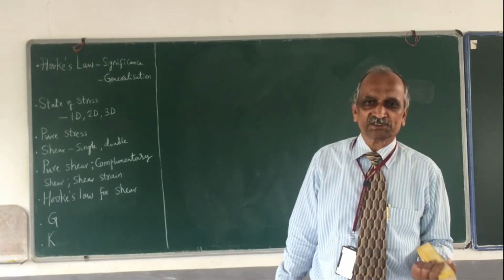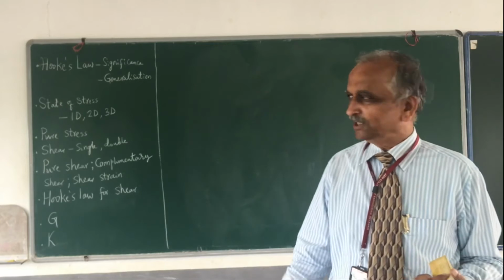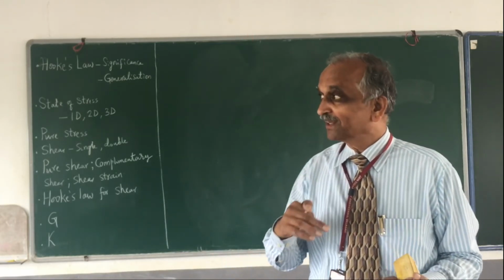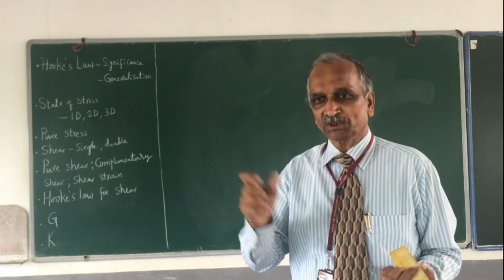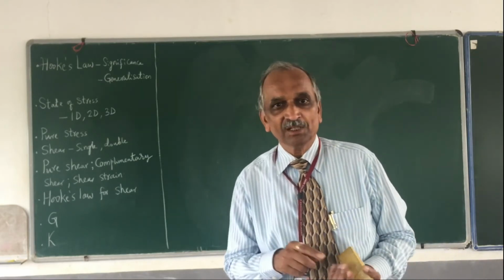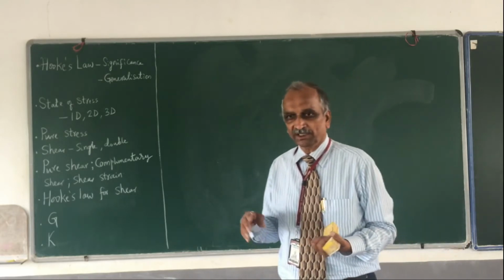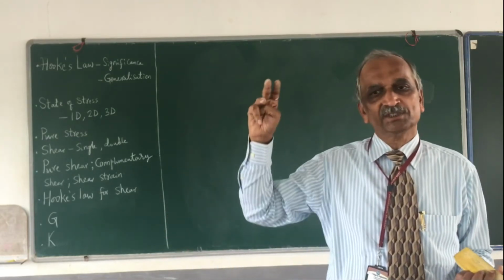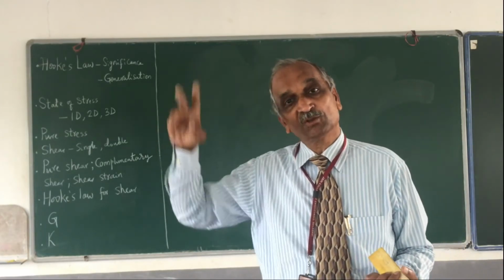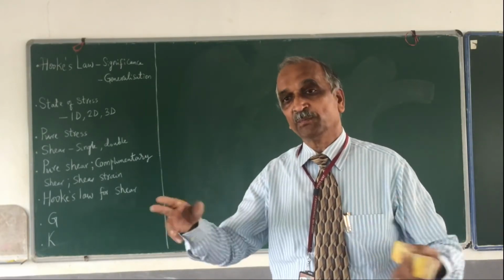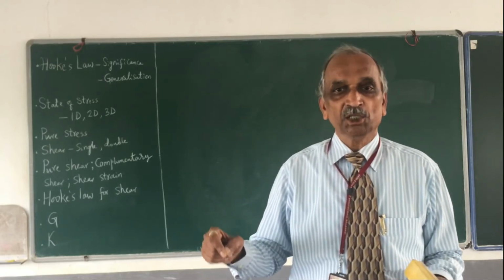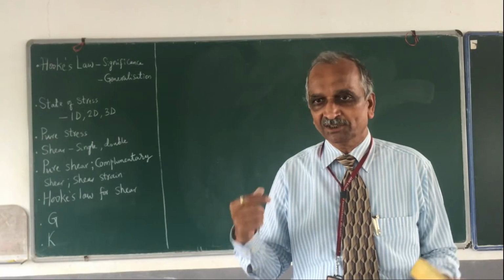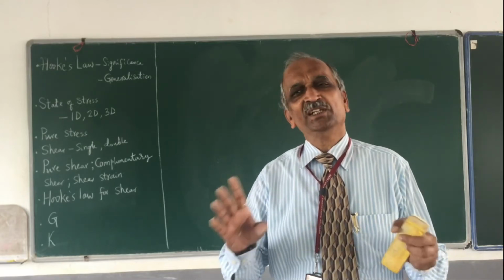How do you express the state of stress? Initially, when I took the very first class, I told you about something called a tensor. Stress is not just a vector, it is a tensor. What is the meaning of that? It has magnitude, it has direction, and it has one more thing. What is that? That is the plane. If anyone asks you to calculate the stress at a point, it is a meaningless question.